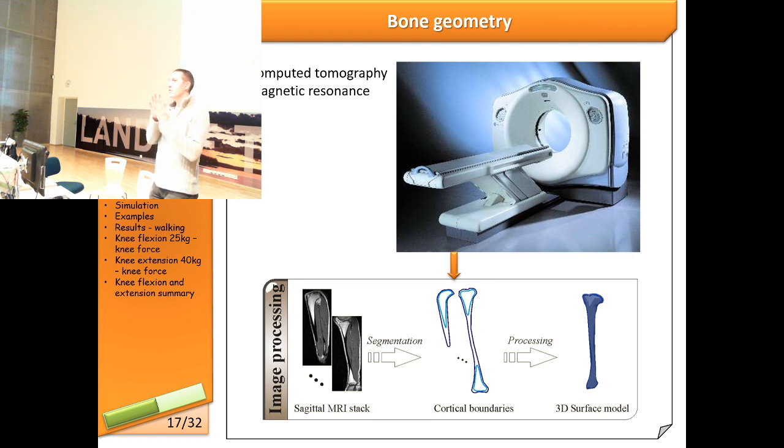And once you have the set of profiles that build up your geometry, you can fit a surface on top of that. So you can have the external surface and internal surfaces if needed, and CAD software can do that for you. And there you get your 3D geometry that you can use in finite element software for meshing. You can mesh only the surface, assuming some certain thickness of the wall, which is quite a simple approach, but not very accurate. Or you can actually mesh the volume. And when you mesh the volume, you can take care of the differences in the bone wall thickness.